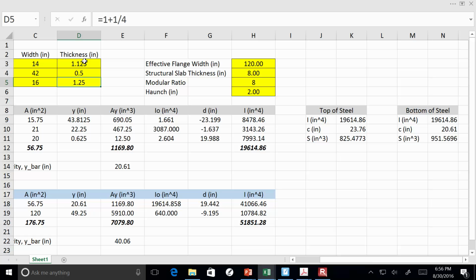I thought about this, and I thought this might be worth mentioning. You all probably are used to expressing things as, this component of the beam is in compression, this component of the beam is in tension, and while that's going to be very important for later, right now what I'm really trying to do is express things as either the top of the section or the bottom of the section. The reason why I'm making that distinction is because in the negative bending region it flips. Usually if I sit on this table, the top of the table is in compression, the bottom of it's in tension. Around the pier, that's backwards. The bottom is in compression. So to reduce confusion, I'm just going to say either the top of the beam or the bottom of the beam. That way we all know what we're talking about. All right, sound good? Okay.